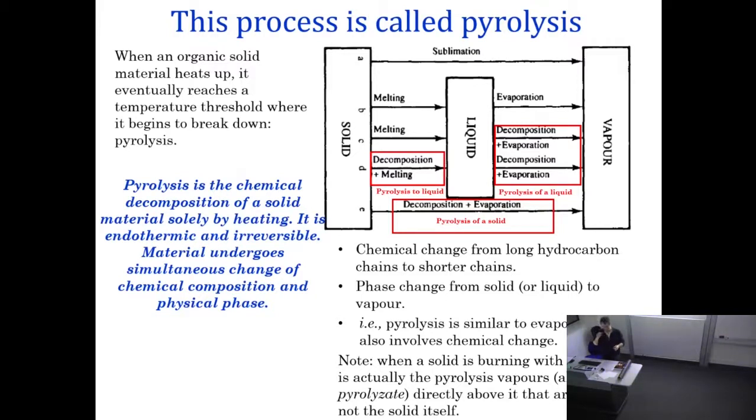But all polymers, except very, very, very specific rare cases, when they burn, they provide many more times energy than is required to pyrolyze them. Okay. So in reality, the heat of reaction for pyrolysis is very small compared to the heat of combustion of exactly the same material. And that's why many materials, when you ignite them externally, they themselves can develop the fire and not self-extinguish, because they can actually use a fraction of the heat that is being released by combustion to pyrolyze the next layer, which then will provide even more heat by combustion, and a fraction of that heat will go into heating up the next layer.